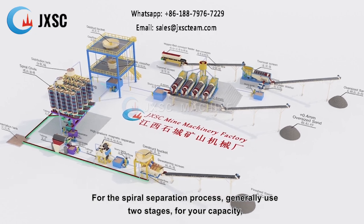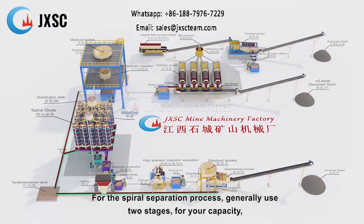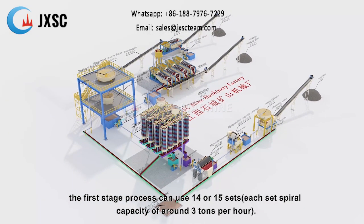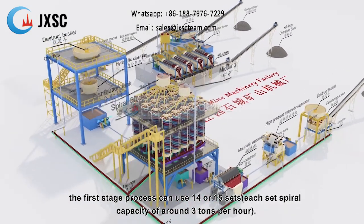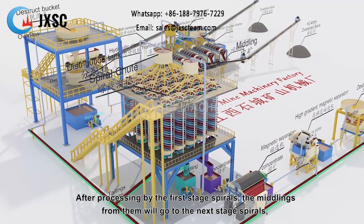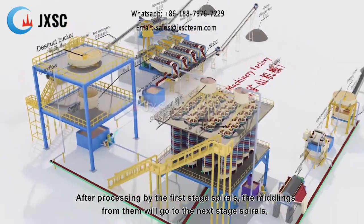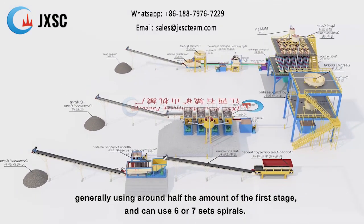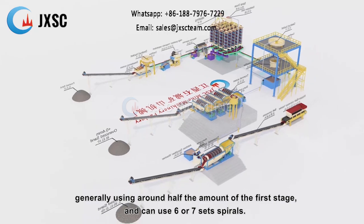For the spiral separation process, generally use 2 stages. For your capacity, the first stage process can use 14 or 15 sets, each set spiral capacity of around 3 tons per hour. After processing by the first stage spirals, the middlings from them will go to the next stage spirals, generally using around half the amount of the first stage, and can use 6 or 7 sets of spirals.